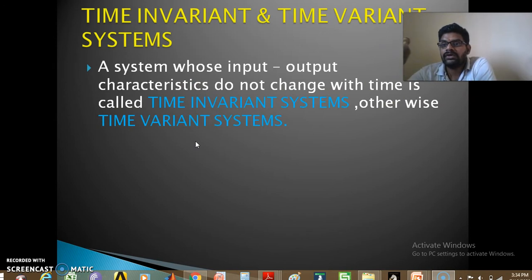For example, a diode changes its cut-in voltage based on temperature. In a transistor we have the IC equation, where the reverse saturation current changes by increasing the temperature from room temperature, or the working temperature of the device.